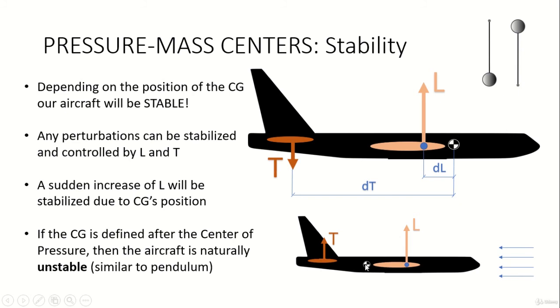The case that we have the center of gravity positioned farther away from the front of the vehicle than the lift, okay? So let's say now the lift increases a bit. If you imagine that you're holding the aircraft at this point, what would happen is the aircraft would start to rotate, and unless the tail can provide stability, which probably wouldn't, the aircraft would just move around completely unstably, in the same way that we defined over here, right?